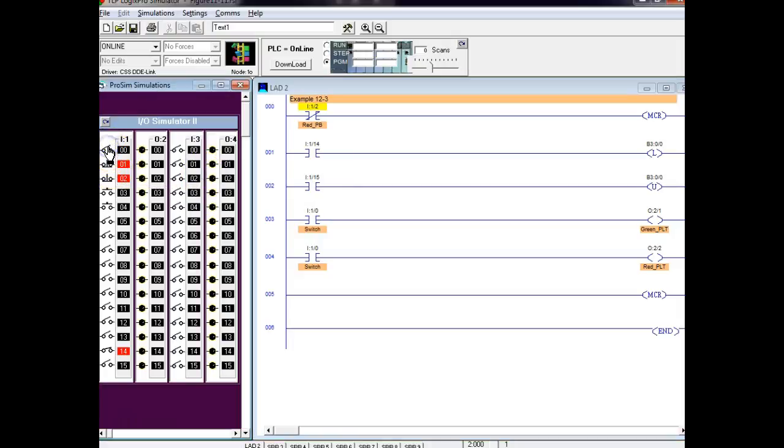Oh, so you added the latch and unlatch? Yeah, I did that because I want to show y'all how it works, the latch and unlatch, how it works, but also what an e-stop button does. Normally we use latch and unlatch relays for very important things that we don't want to go off when we lose our control system. So this is what we were talking about a while ago. Like I said, the only thing that I remember out there that we used latch and unlatch relays for was on our magnets, on our electromagnets, on our cranes.